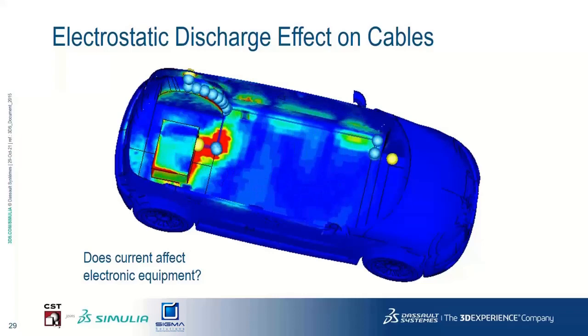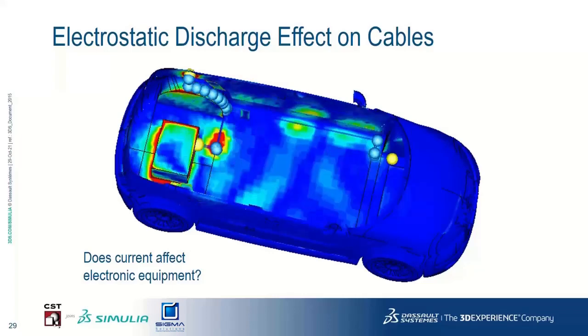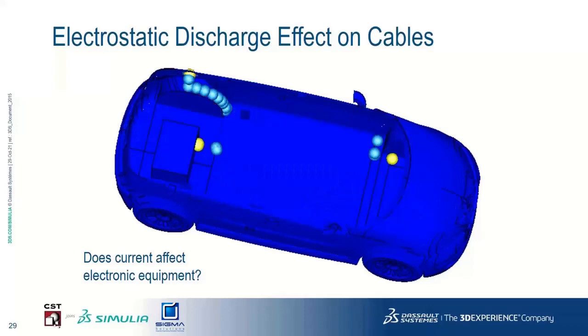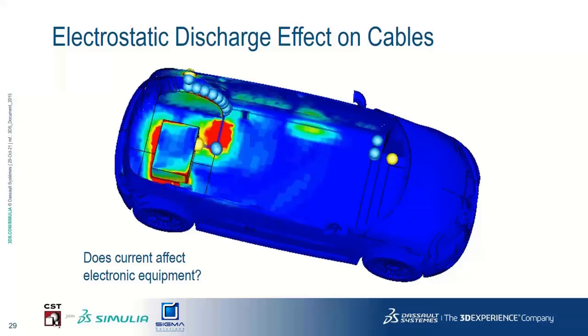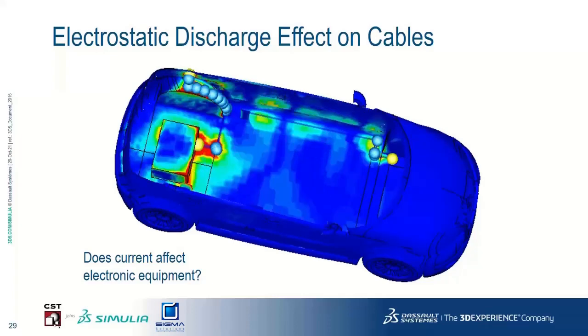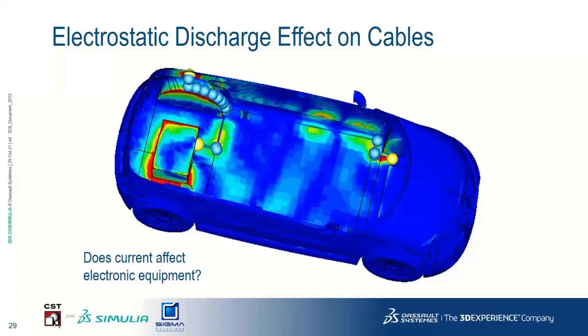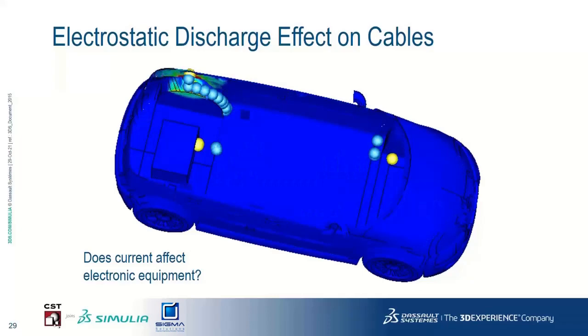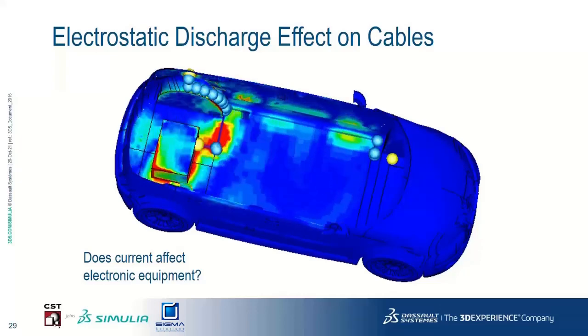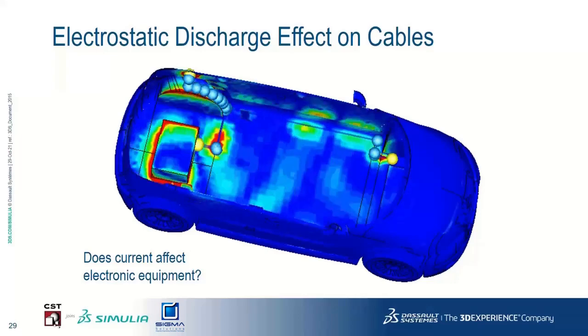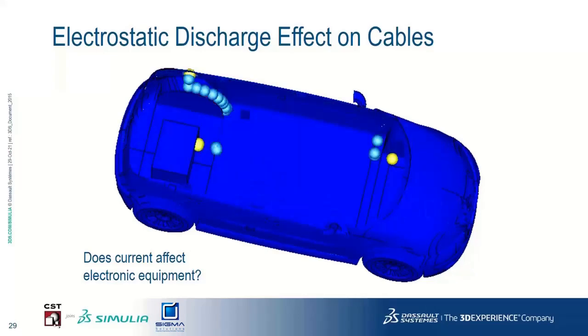So what happens if you open the lid there in order to connect it to power for charging, right? So here we have simulated an electrostatic discharge, and you see how it's propagating, which systems may be affected, and then you can in turn try to bundle your cables differently, or shield them differently, or play around with those kinds of parameters, and see if the problems occurring due to this discharge improve or get worse.